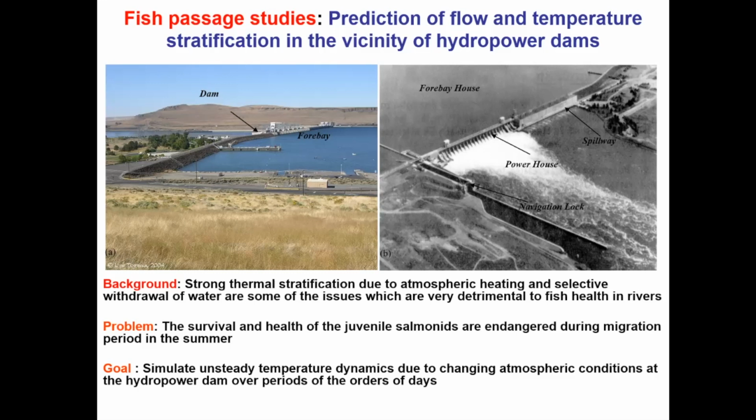And the issue is that some of this fish is going toward the powerhouse units, and from there into the intake, typically 10–15% of the fish, but there are also lots of problems related to the health of the fish. In order to minimize the number of fish going through the intakes, there are two ways of doing that. They have a certain number of what they call fish screens, where they try to retain the fish and then divert them toward a collection channel, okay?